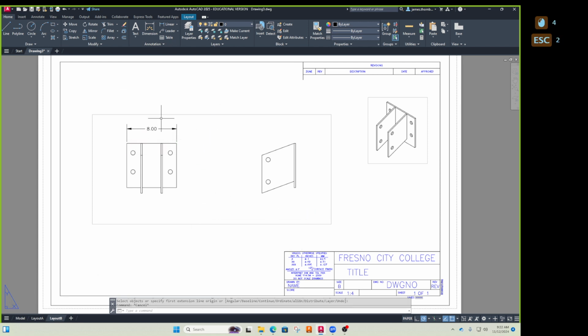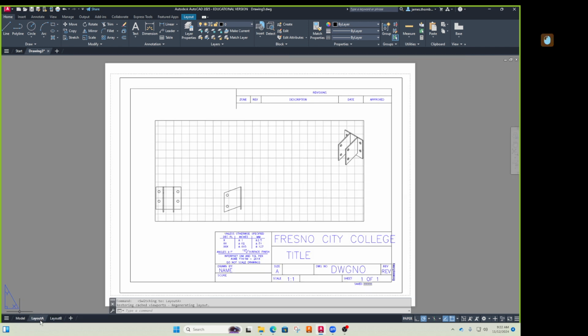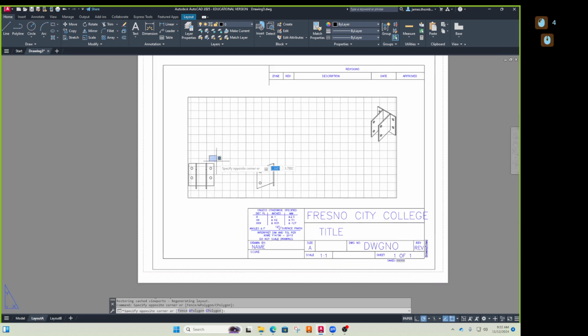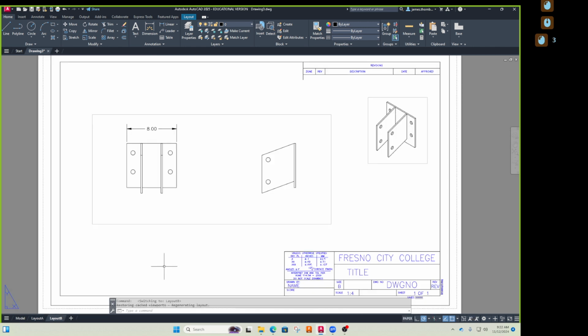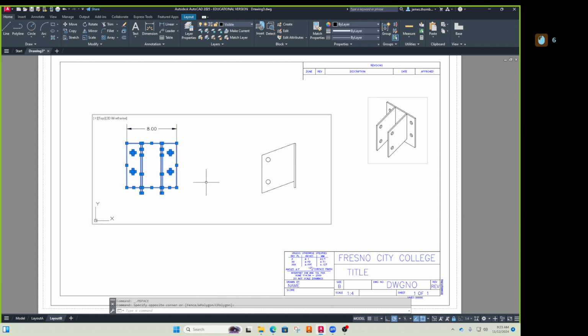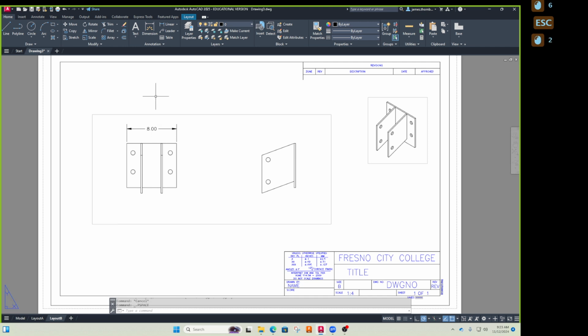So they're in paper space, they put the dimension there, and they do all their dimensions because they think, oh, dimension is annotation, so it should be on the paper. And so they do that, but then they decide, oh, I really want to put it on layout A. Guess what? Their stuff is on this layout, not part of that. But if it's in model space, then I can pop it into a new viewport, do whatever, and it's automatically there.